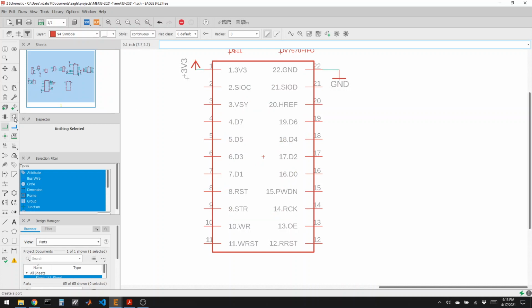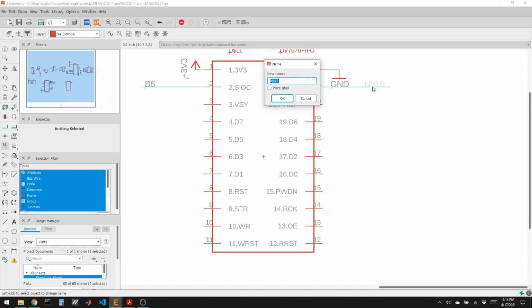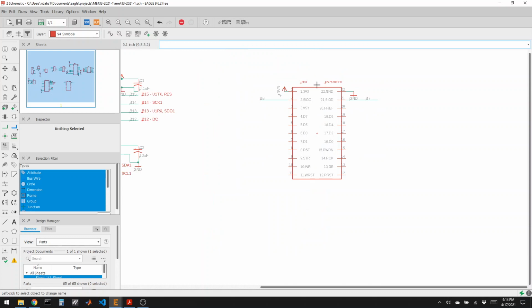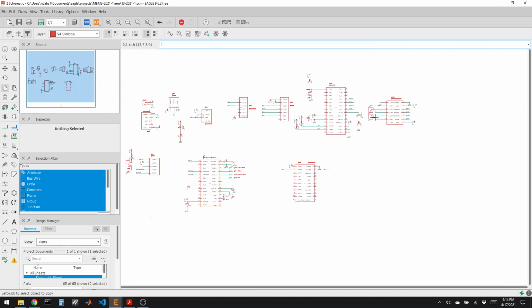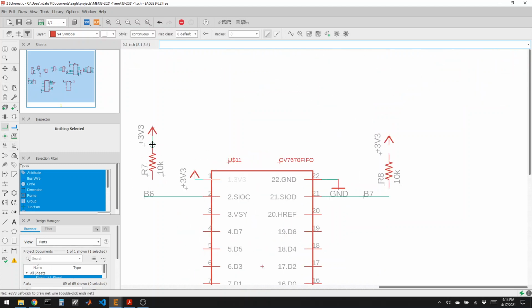And not all of these pins are needed. We're going to go over them in detail later on. I'll just tell you which pins I've selected on the PIC to be able to communicate with the memory chip, and hopefully this works later on. So SIOC, it's kind of like an I2C pin, but not quite I2C. So we're not going to share the I2C bus. We're going to bit bang this. So SIOC, that's going to go to B6 on the PIC. And SIOD going to go to B7. And because this is like I2C, they need pull-up resistors. And I'm slightly worried that 10K isn't a good pull-up resistor, so we're actually going to use a specific value of 4.7K.